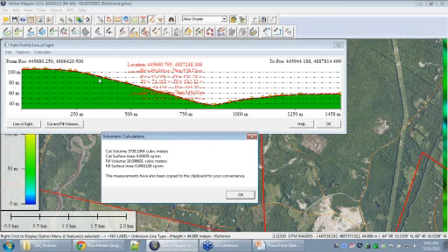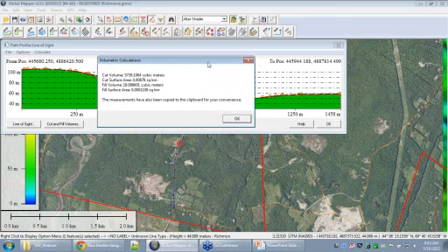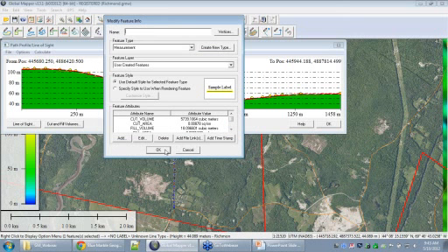As we do the volume calculation, you'll see the extra red line gets traced in on our screen such that we can tell exactly where the digging operation is going to happen on the graphic relative to that surface. Since we only did a shallow cut here, it's going to show up almost right on the surface there. Our pixels are overlapping. If we were doing a deeper cut, we'd see that red line go a little bit deeper into the surface.